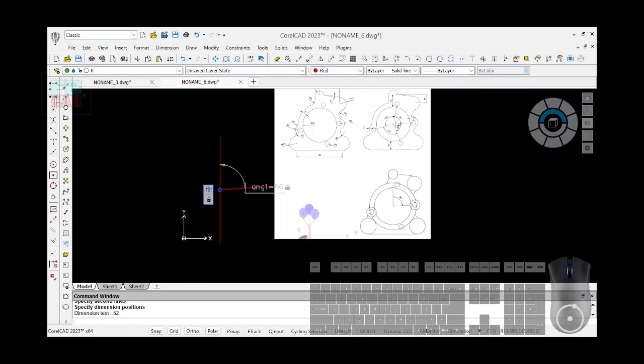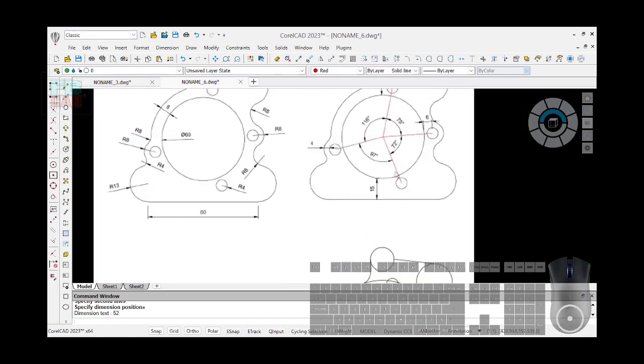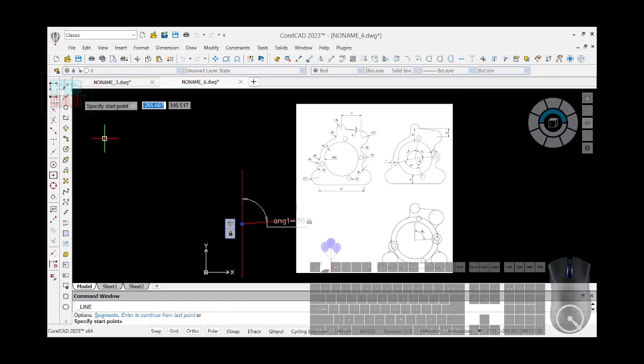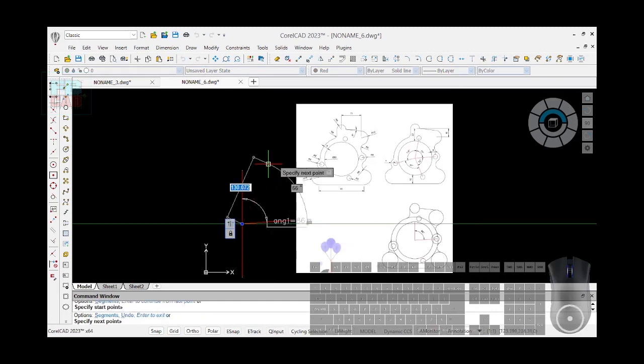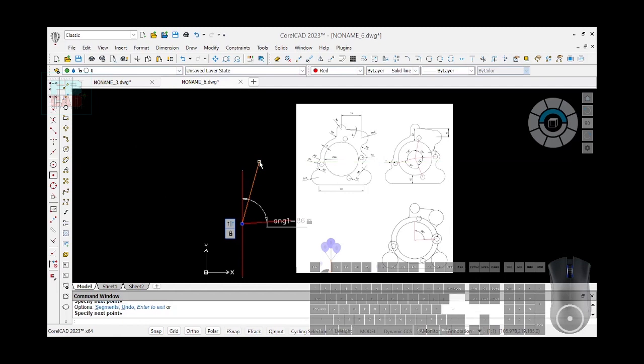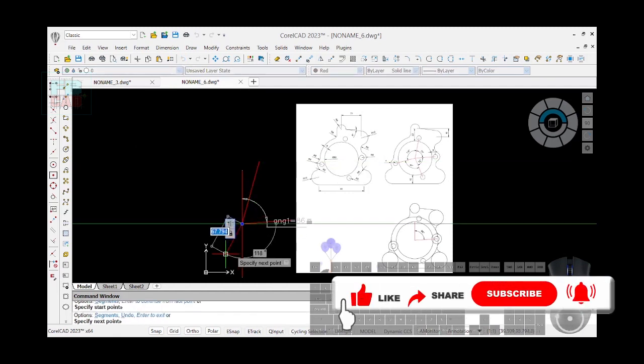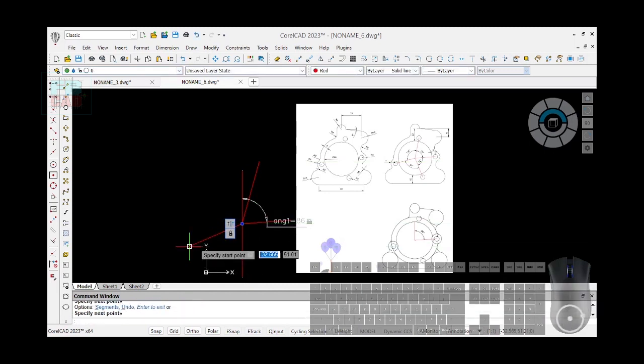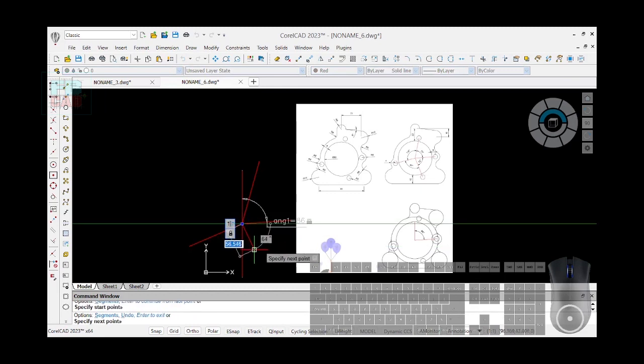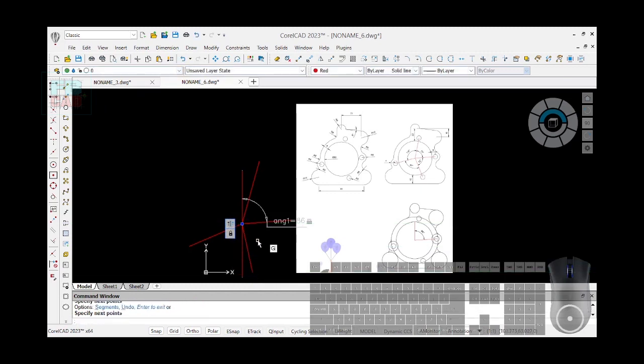Likewise we're going to consider doing this and this too. So I'm taking my line, starting from here, put something here, enter. Start another line from here, come here, press enter. Another line from here, come here, press enter. Okay, geometric constraint coincident, I want all of them to be coincident at the middle of this here. Enter.